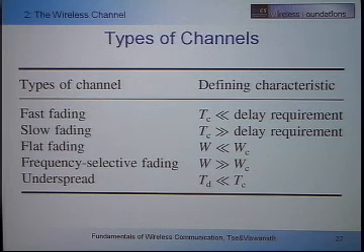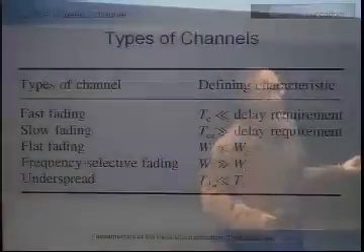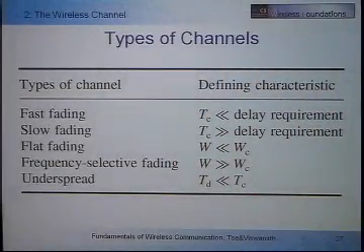Similarly, we prefer a fast fading versus slow fading channel. Because a fast fading means what? That means within the latency timescale for which you have to deliver the traffic, you have an opportunity to see the channel going up and down. And therefore, if it goes down at some time, you may be able to see a better channel next time. If it's a slow fading, then within the latency requirement, the channel is essentially constant. Either it's down or up. If it's down, you're gone. You don't have anything to send. So in terms of reliability, it's not very good. So that's why I prefer a fast versus slow fading, and that's why I define fast and slow fading this way. It's the temporal analog to the frequency domain.